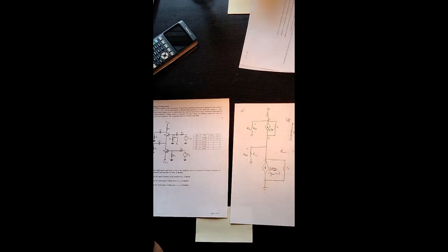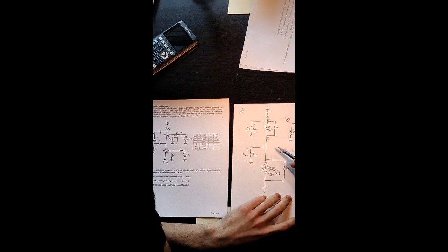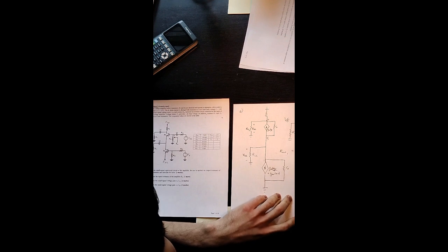Okay. So that does change my argument for the output resistance of the first transistor, I would argue. Because if you raise the drain voltage here, you would get current through R0, yes. But after it's done, it could go either through RL2 or through R0. So I'm going to say it's the output resistance R0 plus RL2 in parallel with R0. A second R0 at the bottom.